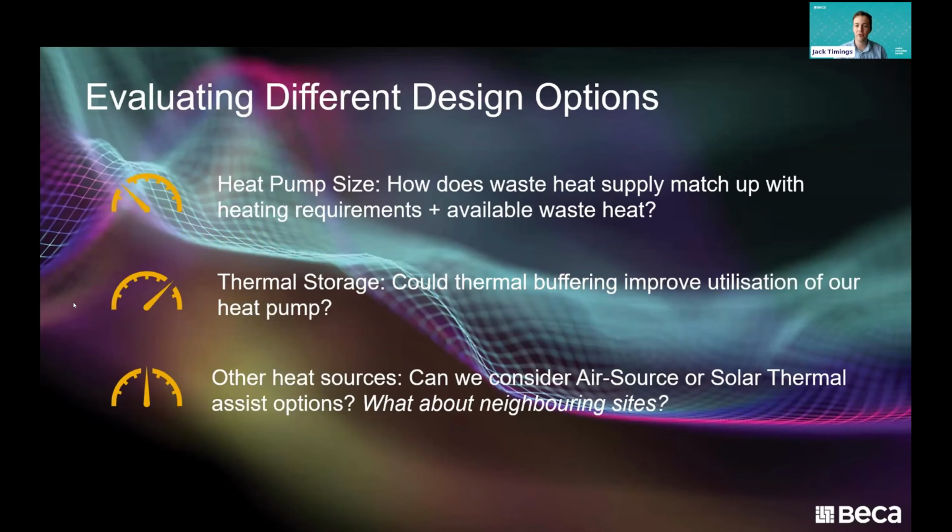So then after we knew we had our data in place and we trusted where it was coming from and we were happy with how the upstream and downstream systems were operating, now we move into cycling through our design options, right? Sizing our heat pump. We tested a number of 4 or 5 different heat pump sizes in a model, understanding what kind of waste heat we had available and what kind of heat demands there were on the site before we picked something.